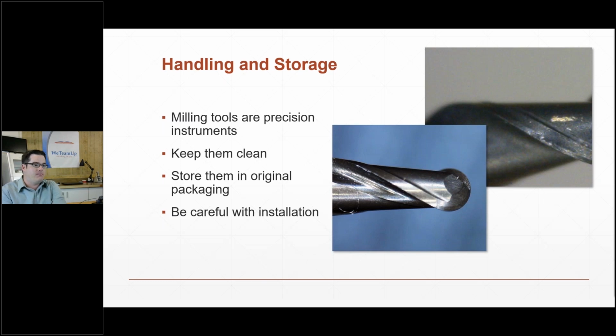So we recommend keeping them clean, and if you're going to take it out of the machine and store it, put it back in its original packaging. And then one of the biggest things that we see is damage during installation of the tool. So when you're putting the tool in your machine, be very aware of where the tip of it is, and make sure you don't crash it into any little pieces of metal or the tool holder or whatever.